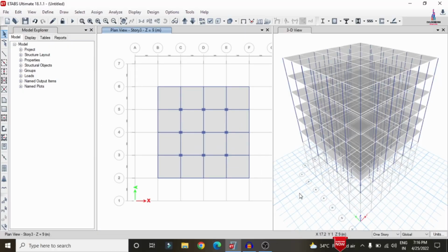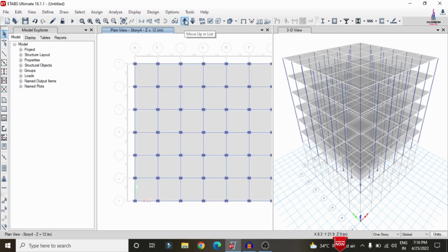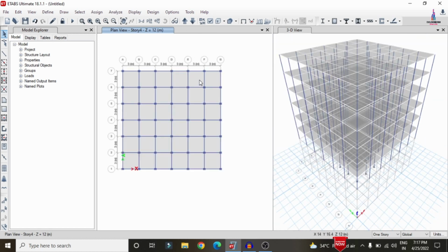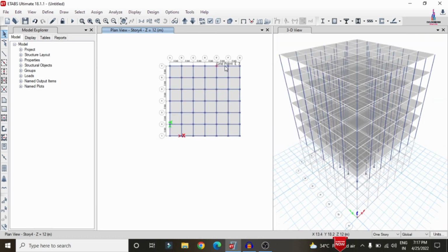Now we can see here I have deleted all the column sections at the corner section. So now we have to proceed with the remaining floor section for the respective property. For that I am going to the top section. Again it will consist of your respective property here like this. Now we have to delete all the external columns for this respective floor section.